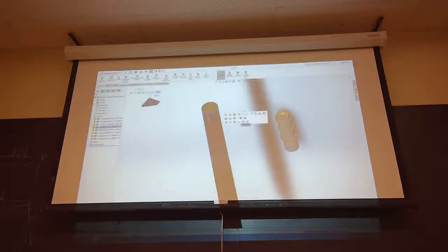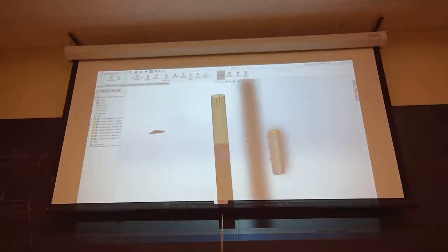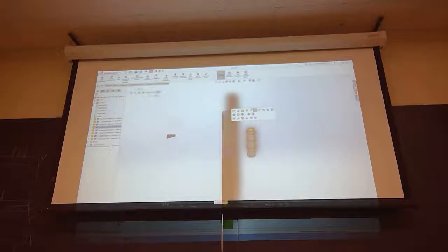So it's concentric mating again? Anybody not there yet? Okay, then I'm moving on. Everyone good? Okay, sweet. It was just transparent. That's why it looks funny. Is it just concentric or are we also doing coincident to get the ends to line up? Yeah, it's going to be concentric, and then you want to make it coincident so that it's flush with the ends of the two. Cool.